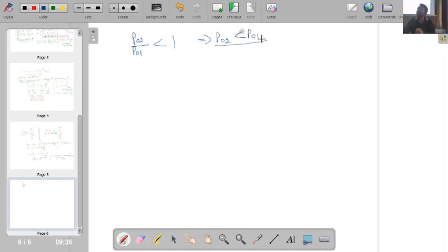Is this one clear? So it means that across the shock wave our stagnation pressure actually decreases. In the downstream of the shock wave we have less total pressure in comparison to its upstream. Okay, so that is the reason that flow is possible. I just now posed you a question, whether flow is possible or not. So our static pressure P2 is becoming high on the downstream of the shock wave. So P2 is becoming greater than P1, but stagnation pressure or total pressure on the downstream of the shock wave is actually decreasing. So this is the reason that flow is possible from left to right despite the fact that static pressure is increasing, because flow is governed by the total pressure. Okay, is this point clear?